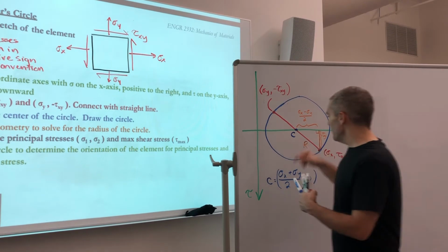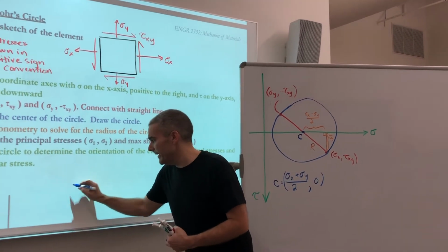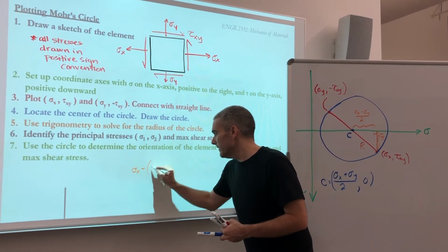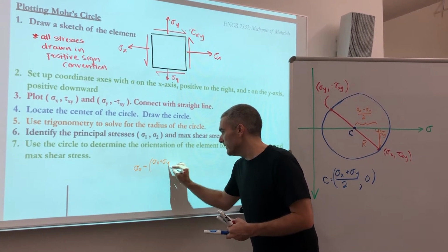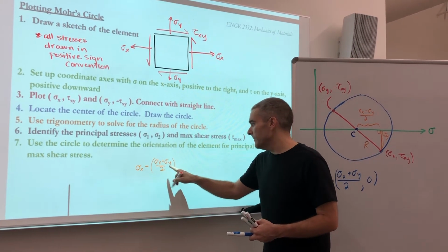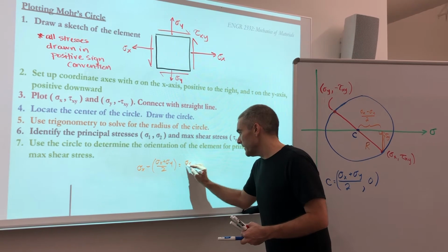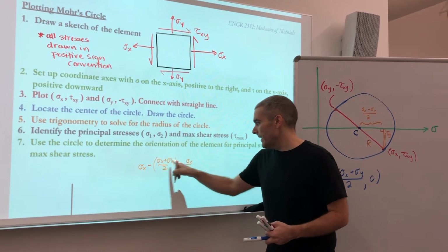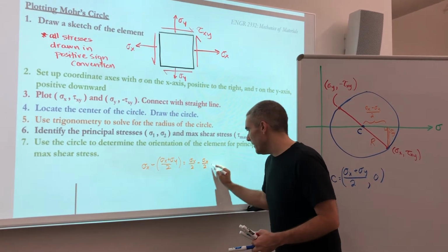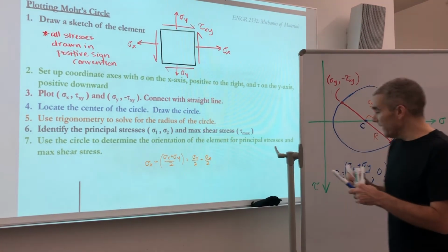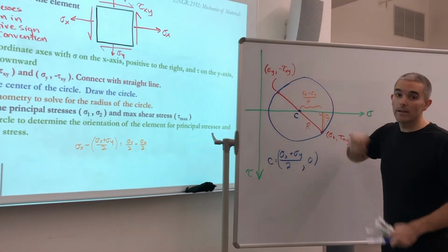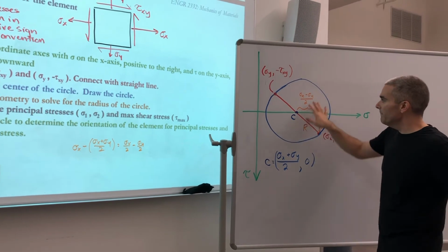And if we want to do the math real quick there, we can. We wanted sigma x minus the center. So that's going to give us sigma x minus sigma x over 2, which gives us just sigma x over 2. Then we have a negative that gets distributed, minus sigma y over 2. I put them under the same denominator, and I end up with (sigma x minus sigma y) over 2. Alright, so hopefully you saw that with the algebra.